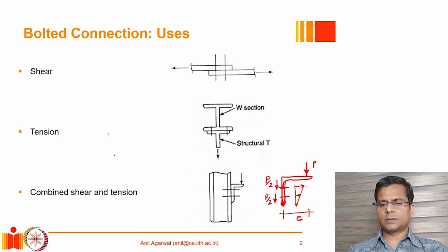These individual forces, let's call them X and Y, in the horizontal direction will produce enough counter moment to balance the total moment of P multiplied by e. So this way we can see that these bolts are not only subjected to a shear force of P divided by 2, but also an axial force of X or Y respectively.